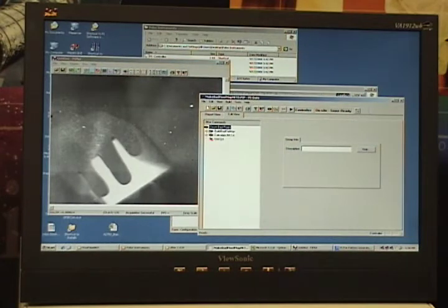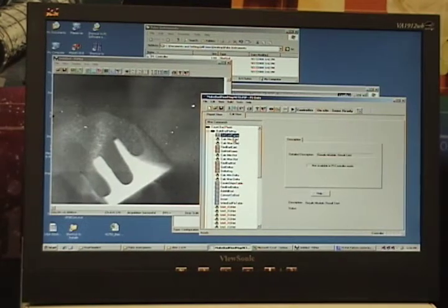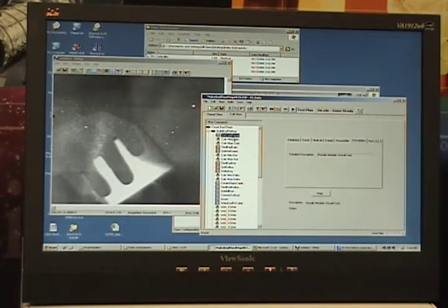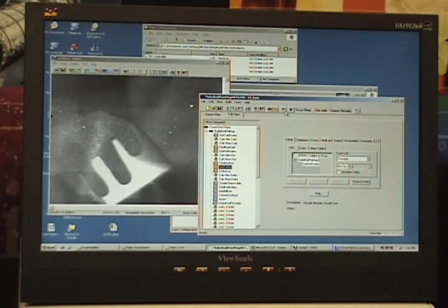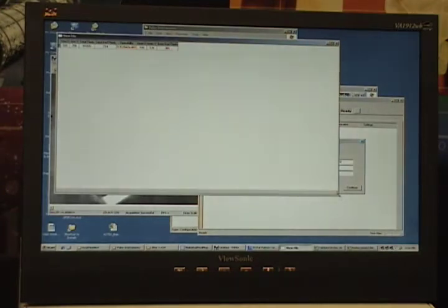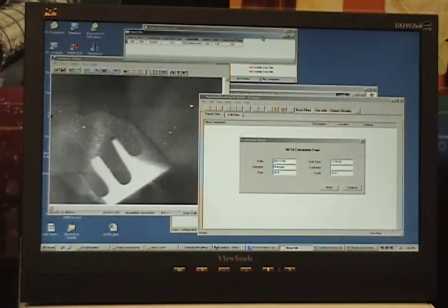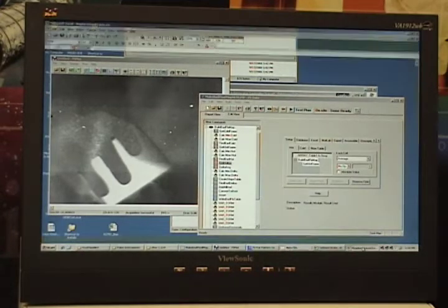As you can see in this test plan, we have a graphical analysis feature that allows mathematical analysis without writing any code. This example uses a threshold of 3 sigma from the mean to determine which pixels are bad, but you can use any threshold value or voltage that you want, depending on the characteristics of your device. When we run the test plan, it tests each pixel's responses against these thresholds, then marks each bad pixel location. It can also read the temperature from the blackbody controller and use this to calculate responsivity and NETD.